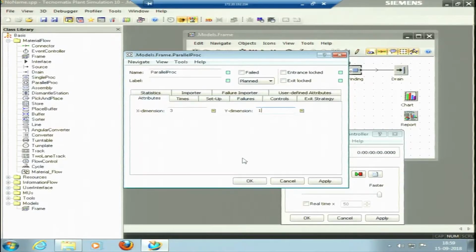So if it is kind of a process layout, it would be a batch production or job production. In case of batch production, another batch could enter so that there is no idle time. Actually not exactly no, but the minimum idle time is there. The machines are working at full capacity if possible. So we can try that in simulation before actually doing the scheduling, then routing, all those things that we learn in production planning and control. That can all be done using this simulation.